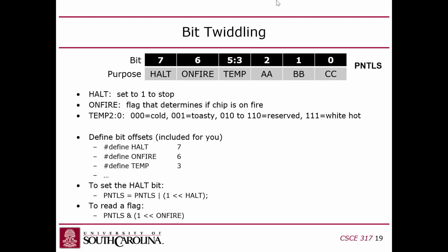Something else that's probably important to point out here is that you might be going, well, isn't that 2 operations? Because you've got a left shift, and then you've also got an OR, and then you've got a set, so that's going to be like 3 instructions. It actually turns out that the ARM instruction set has instructions for doing things like reading and setting a single bit, and ARM GCC just has enough magic compiler juice in it that it knows what you meant and will